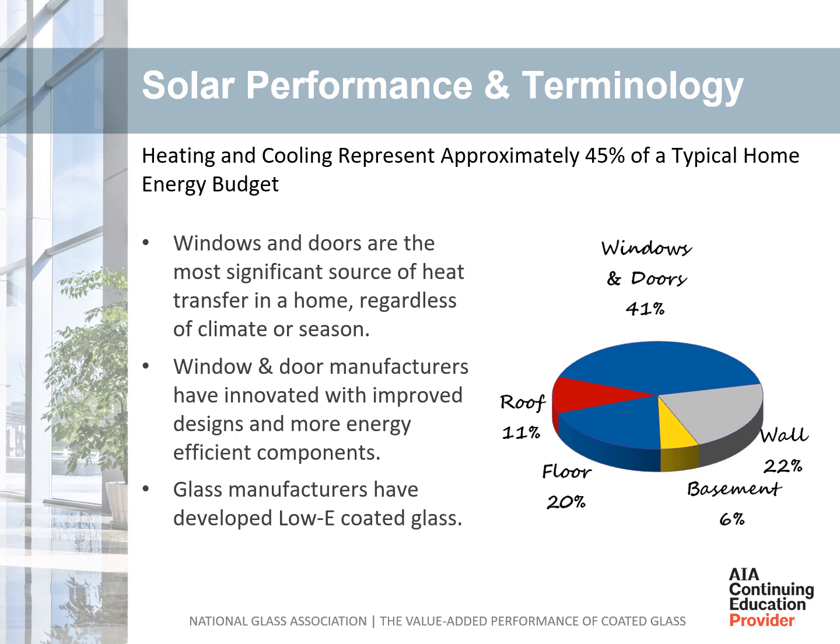There is a reason that window and door manufacturers offer coated glass in their products. Studies show that fenestration products represent the greatest heat losses in a building. This pie chart shows typical residential heat loss, with fenestration accounting for 41% of the dwelling's heat loss. Considering that energy is becoming more expensive, conserving it is one way for the building owner to save money. The product most used to conserve energy loss through glass is a low E product.